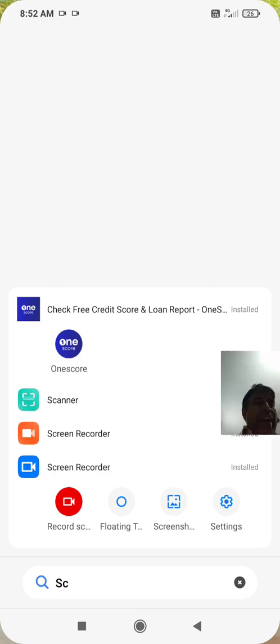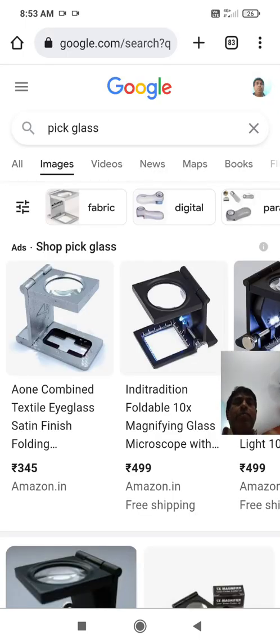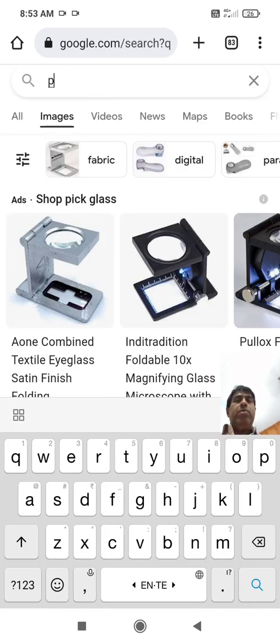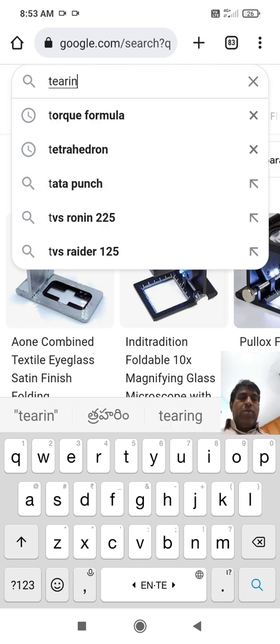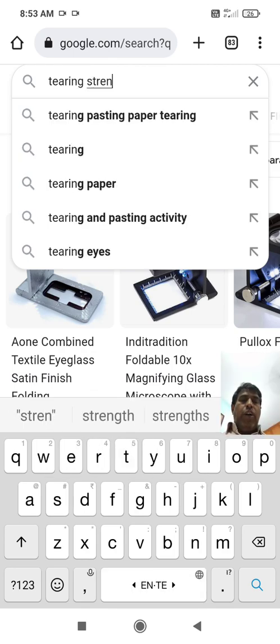And we have the ASTM standard books. The ASTM standard for the tearing strength test method by the trapezoid procedure is ASTM D5587, and for the tongue tear test it is ASTM D2261. Now I will show you about tear strength. First I will show you a picture so that you will know what the tearing strength of fabric is.